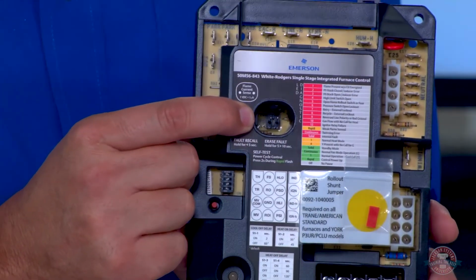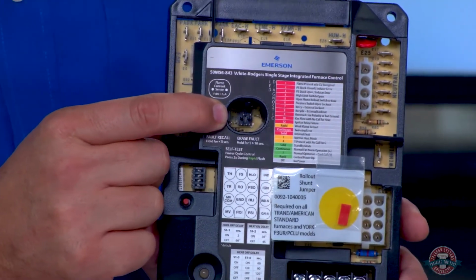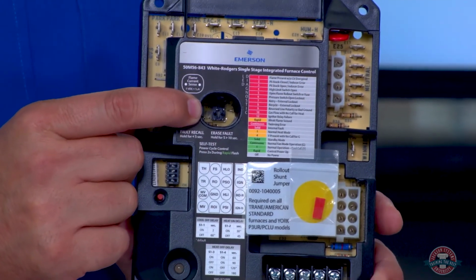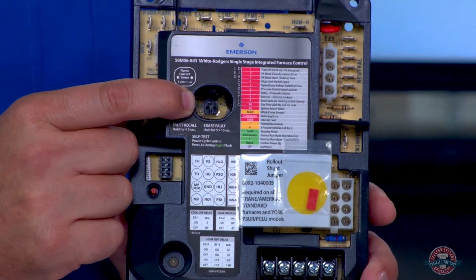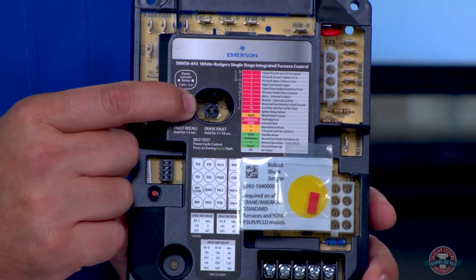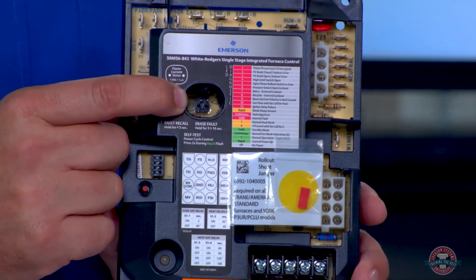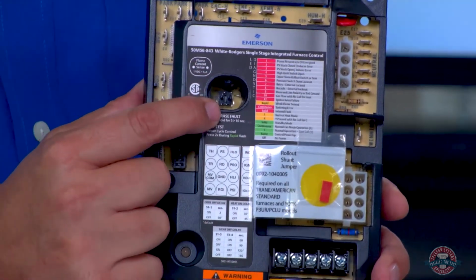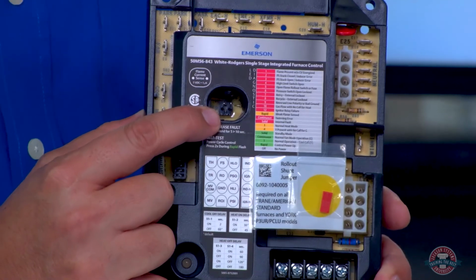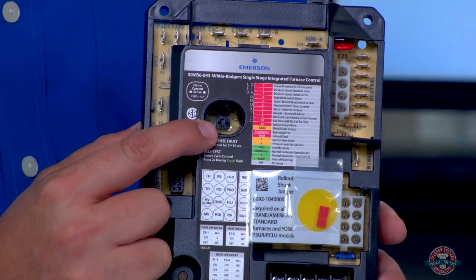That is here towards the top of the board, something that I really want to point out. Universal, since we're speaking about things we have that your OEMs aren't, this is definitely a plus. Right in here, there are two little pins, and those pins are taking the reading of the flame sense.